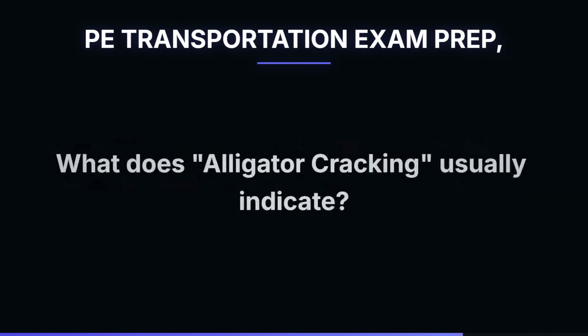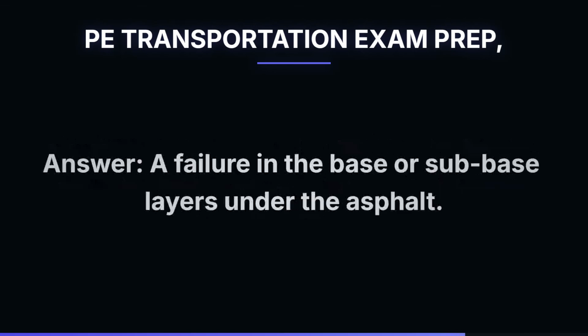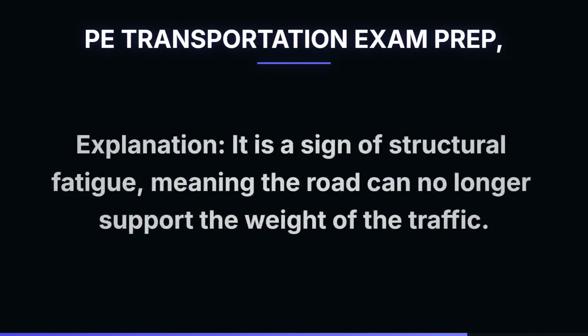2. What does alligator cracking usually indicate? Answer: a failure in the base or sub-base layers under the asphalt. Explanation: it is a sign of structural fatigue, meaning the road can no longer support the weight of the traffic.